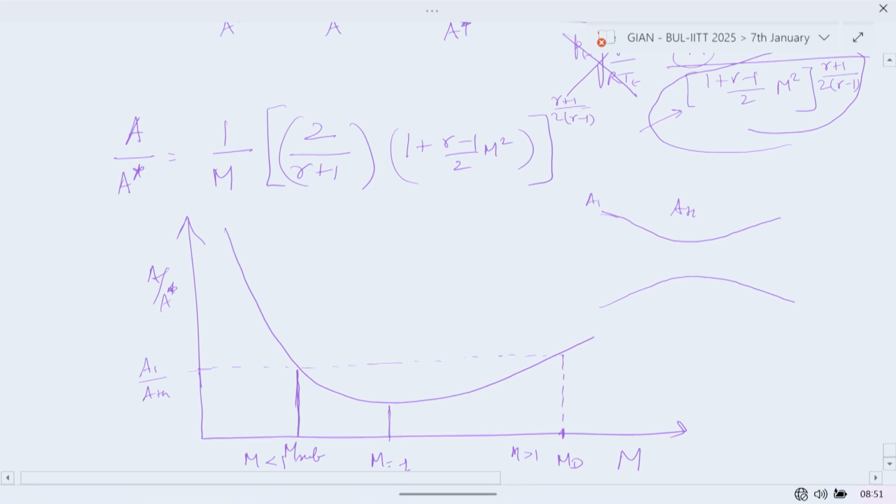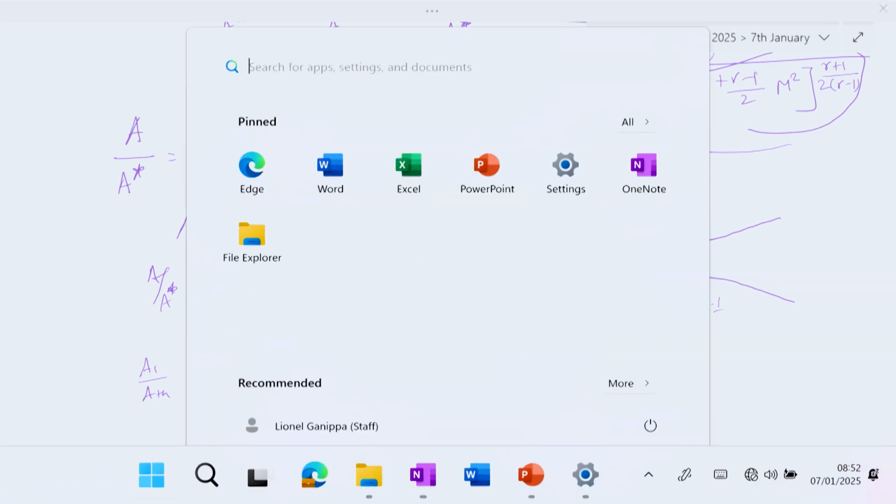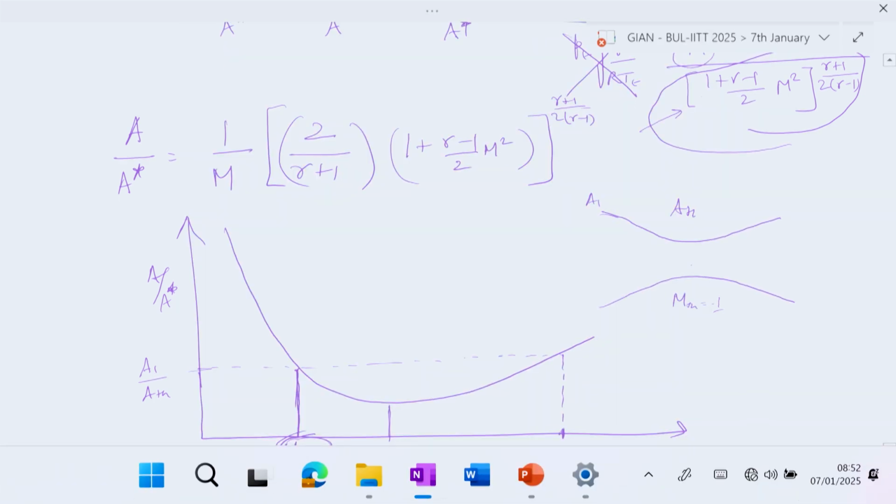Even though I have designed this inlet to operate at supersonic speeds, it has a unique subsonic solution, which makes it even more complex and difficult, because at this unique subsonic solution, the flow gets choked at the throat. At this condition, at subsonic flow, the Mach number at the throat will be 1. It adds a lot of complexities. Okay, so that's what I'm going to discuss now.